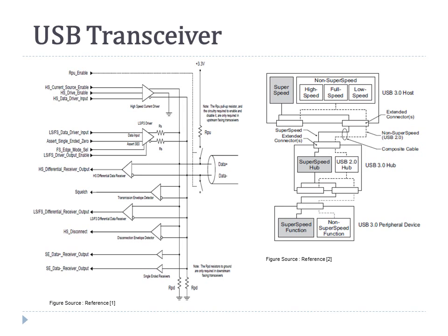Similarly, super speed also works as a feature in parallel to the other speeds of operation. So if a device does not have super speed, it doesn't need to include the super speed circuitry, but if it has super speed, it has to include the super speed circuitry and also support the lower speed modes.